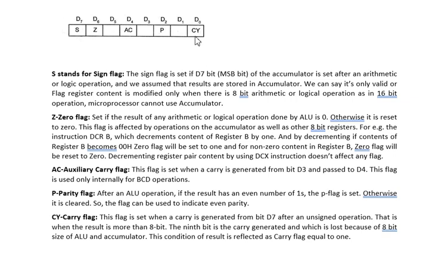Similarly, we have the D0 carry flag. This is called the carry flag. After an addition operation, if a carry is generated, so we have taken two 8-bit data and the result generated is 16-bit. It generated a carry. Say FF plus 01. If you add FF and 01, FF becomes 00 with a carry 1, isn't it? So in this case there will be a ninth bit.